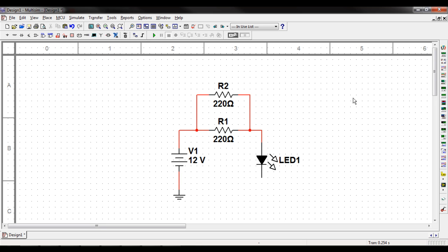There's also another trick. If you double click anywhere, it'll place a node for you, and if you double click, you can end the wire anywhere. So that's a good trick to know if you're doing a lot of complicated wiring and you want to keep things looking neat.